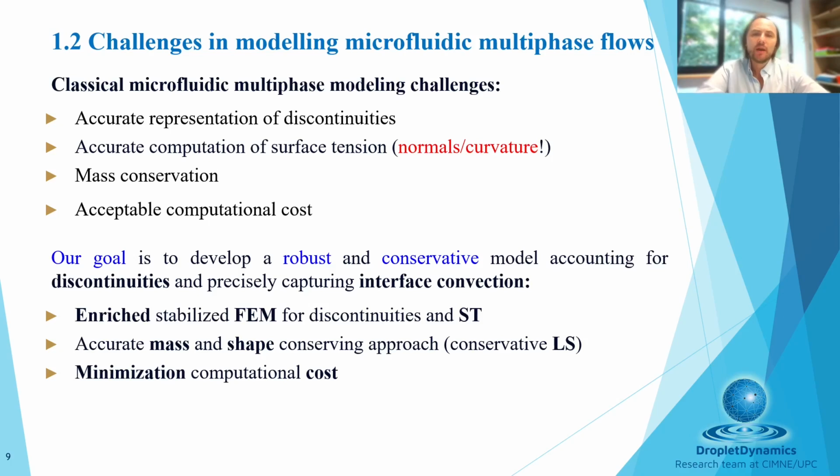So we have proposed an enriched stabilized finite element method for dealing with the two-phase flows. I will speak about it, but the main goal of this method is to capture exactly or very accurately the discontinuities at the liquid-gas interface. And as we know, in microfluidics, surface tension plays a major role.